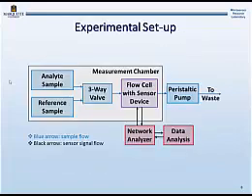Now this is our experimental setup. So similar to a groundwater monitoring well, we place our sensor device and the samples inside a closed measurement chamber. So the analyzed sample contains the BTEX, and the reference sample has been filtered to strip it of the BTEX compounds. And the three-way valve is selected such that we can switch between those samples without interrupting the sample flow. This is important to keep an undistorted baseline. That's important in turn for the response time constant evaluation.